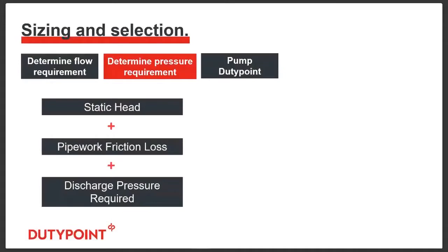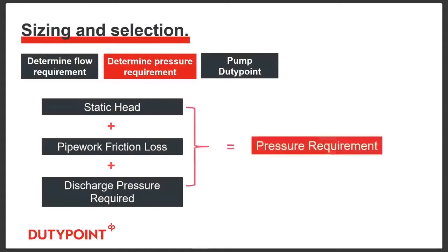You also need to think about the type of sanitary fitting, so the size of the shower, the pressure requirements of the shower, and whether there are other things there like body jets and a lot of these things that you might find in more luxury dwellings. And that added together will give you a pressure which we typically measure in bar, but it can be measured in meters as well. So I hope that makes sense so far.